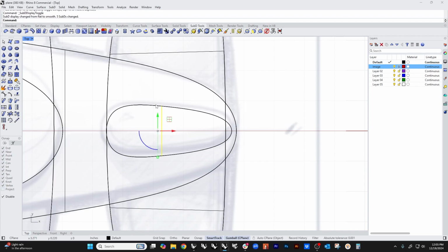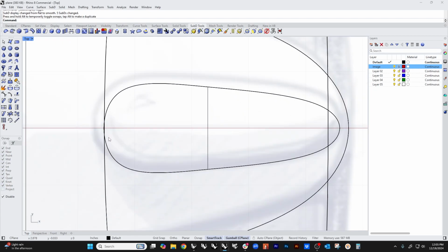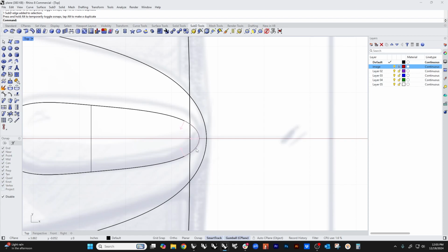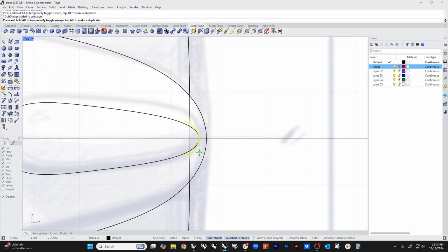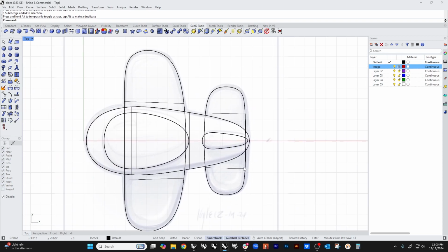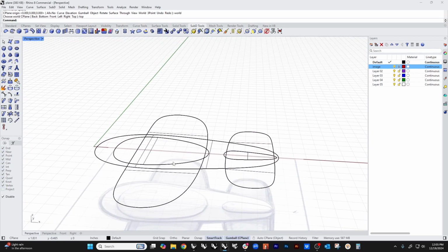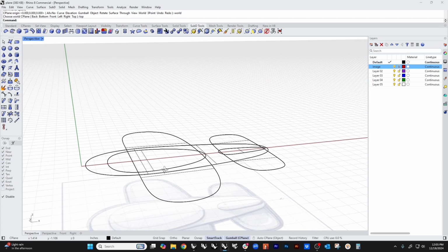And that gives us a little bit more control over the shape because now I can control what's going on there. And then I might grab this edge, pull it forward a little bit, and I might grab this edge and scale it a little more tapery. All right, so we've done most of the work that we need to do, and we haven't really done anything other than lay out a single plane and extrude a couple of edges. We used Control-Shift-click and extrude on the gumball, Command-Shift-drag extrude on the Mac. And we basically are at a point where we can start having some fun with this.